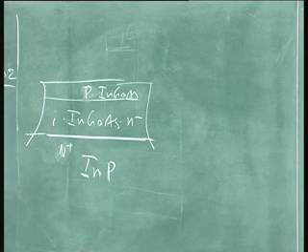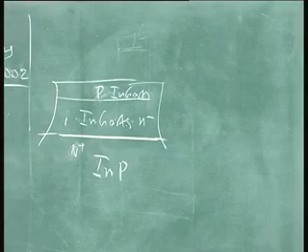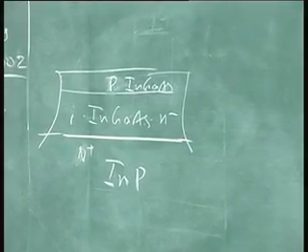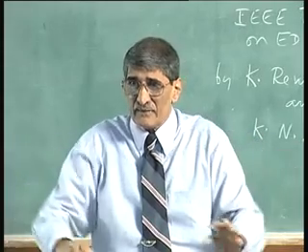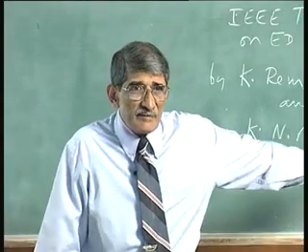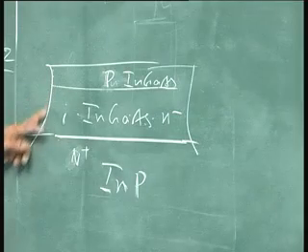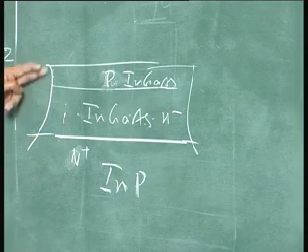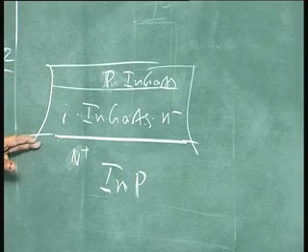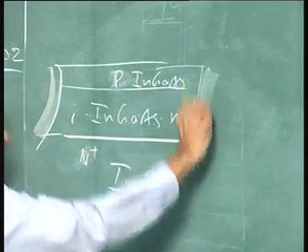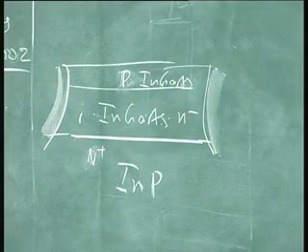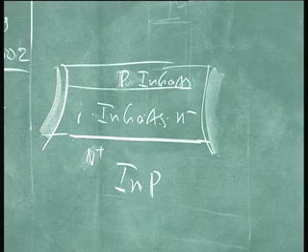When you have the junction exposed, the whole thing what you have to remember is a PN junction is fabricated using epitaxial layer, you etch it down, so that you isolate one device from another one, because on the wafer a number of devices are there, this surface is exposed. That gives rise to large leakage between the P and N layer. You passivate it, and this passivation is again ammonium sulphide which is being used.